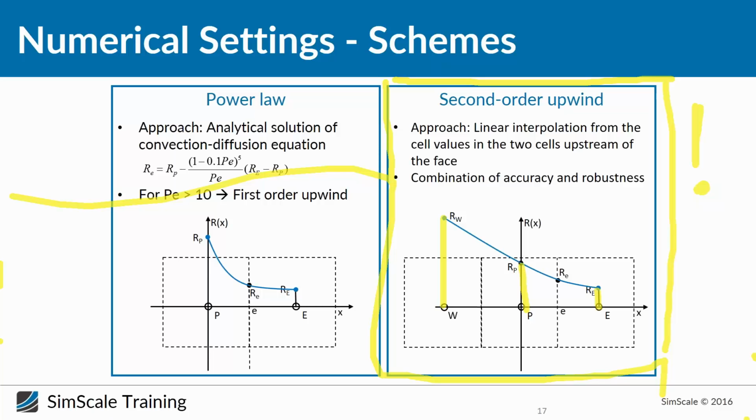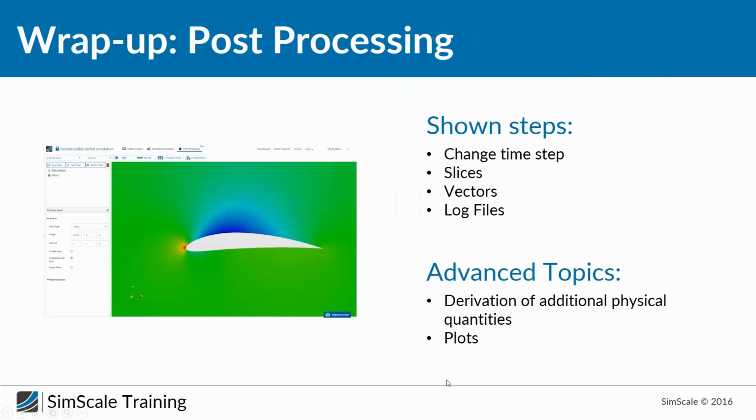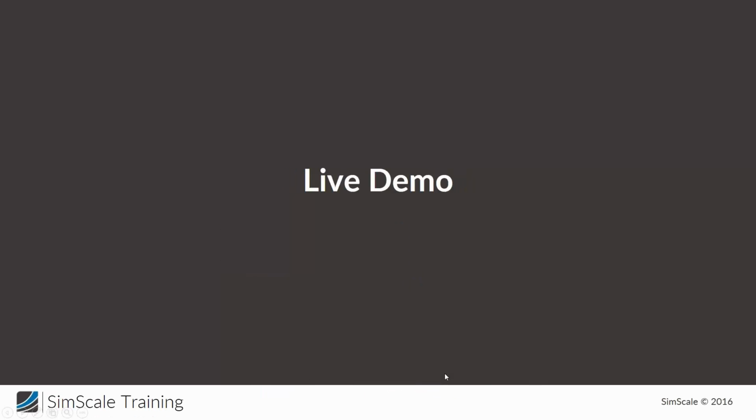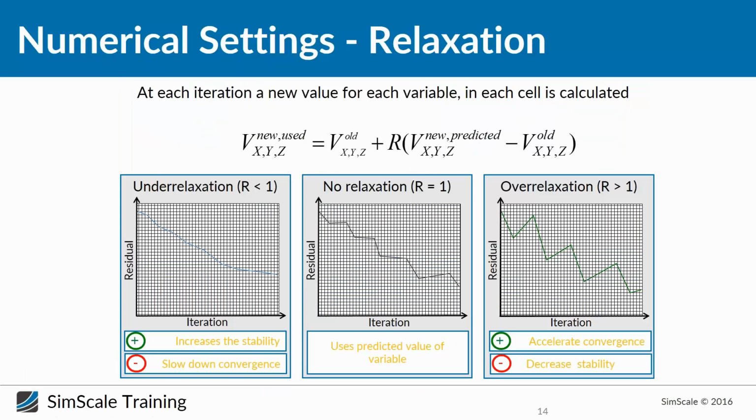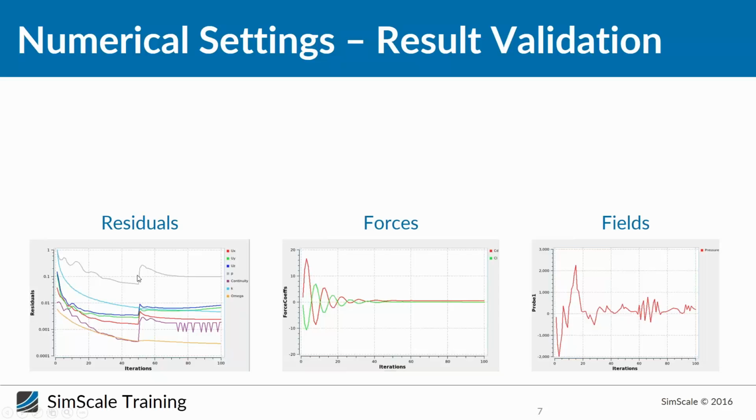Gerasimos, that's a very good question. And basically you're right. For sure, if you would just see this graph here, you cannot really say what happens. For example, if you initialize with velocity 0 for the initial field, that can be the point where the air is hitting the wing, or where we have a flow separation, but it can also be related, and in this case it's really related to a change of the schemes.